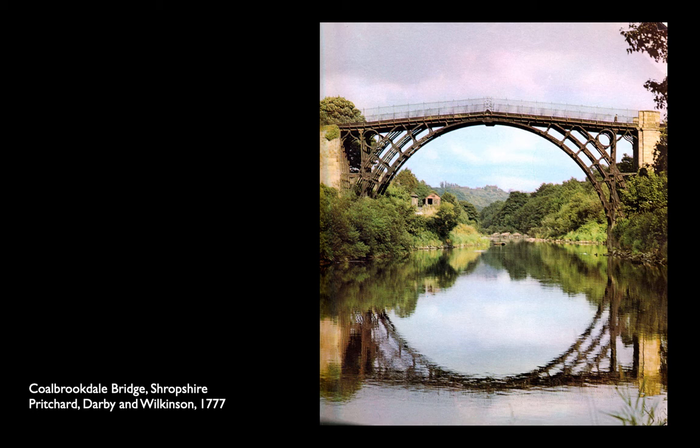And you can see too that it is a pretty impressive span, and it achieves that span because it doesn't have the dead weight that a masonry arch would have. It only has to carry its own relatively light weight, the weight of the iron arches, instead of the heavy weight of the masonry. And as a result, the bridge is able to span with much less material, which puts less stress on the foundations, among other things.